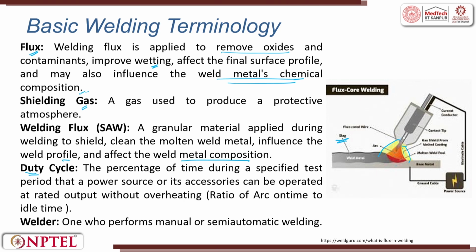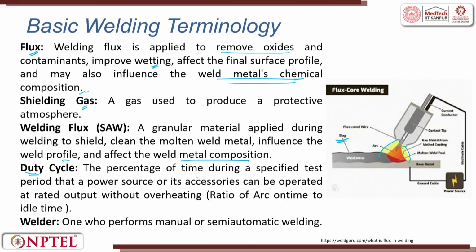Duty cycle is the amount of time the arc should be on, and that is always defined as the duty cycle. The percentage of time during a specific test period that a power source or its accessory can be operated at rated output without overheating is called the duty cycle. Basically, duty cycle is defined as T on divided by T on plus T off, time on divided by time on plus time off.